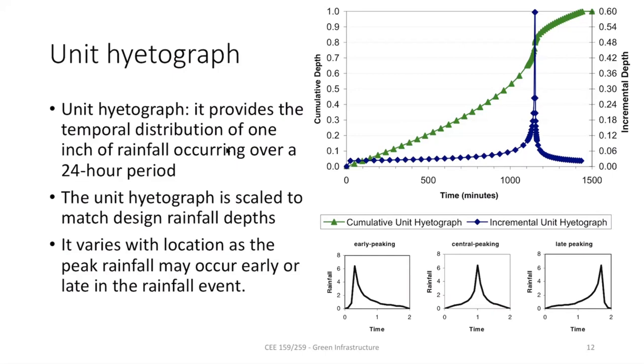Let's say this is a rainfall. What you see here is the depth at different times. Initially it was very small rainfall, then suddenly it's rising, and it rains a lot, up to 1 inch after a certain time, and then it falls quickly. If you do cumulative depth, basically adding them together, it's rising, and then you see this. This is called cumulative depth of incremental rainfall depth. That distribution will also tell you what type of rainfall it is, and it tells you a little more about how you should design the green infrastructures.